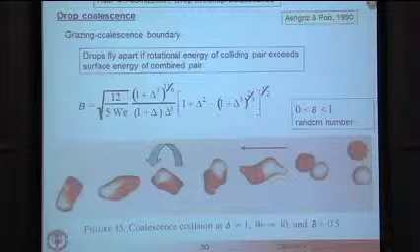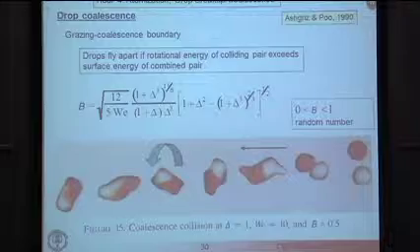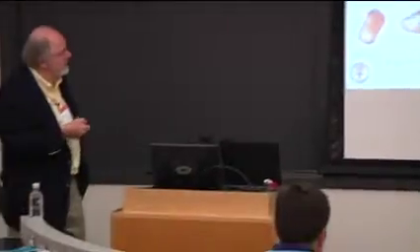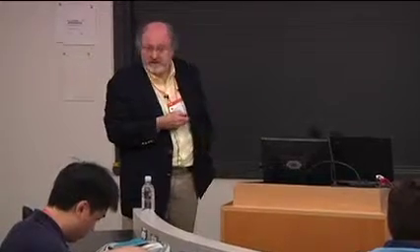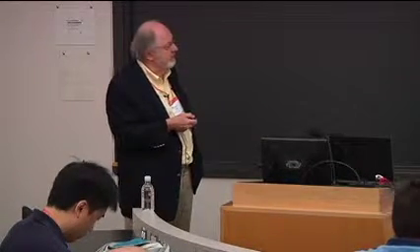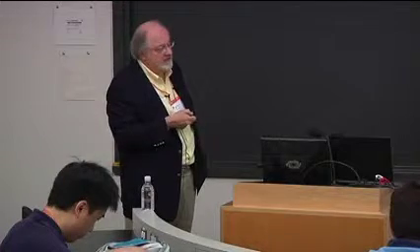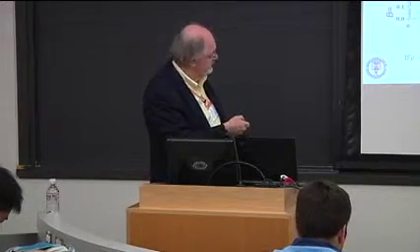So how do you use this in a CFD code? Because all of this is happening subgrid scale, right? We're not modeling any of this stuff directly. We use the idea that there's a stochastic process. We pick a random number that gives us the impact parameter, and then we check to see if this is satisfied. If it is, we go back and take a look and see which regime we're in, and if it's in this coalescence regime, then we use that result.